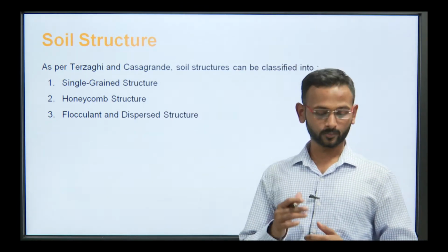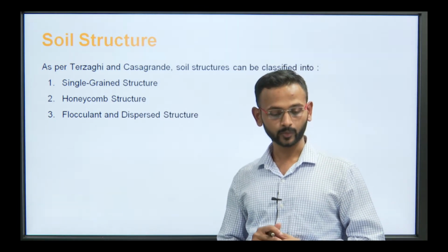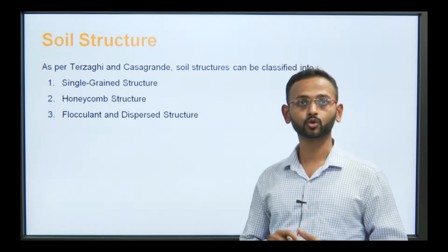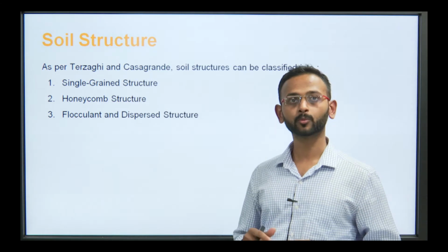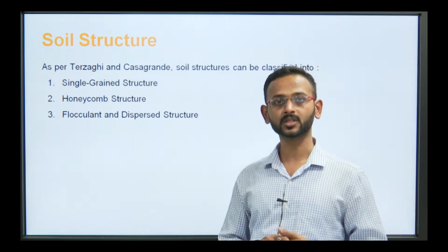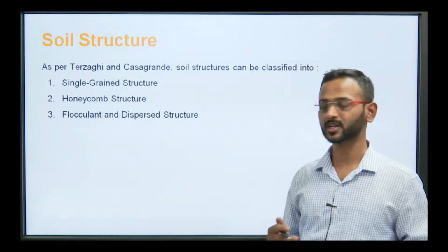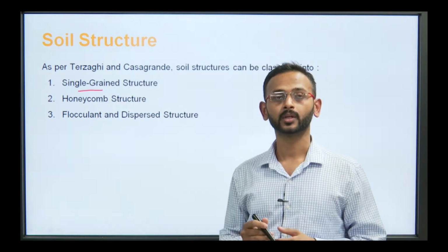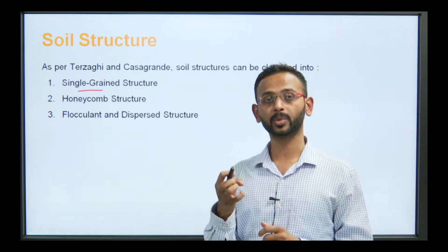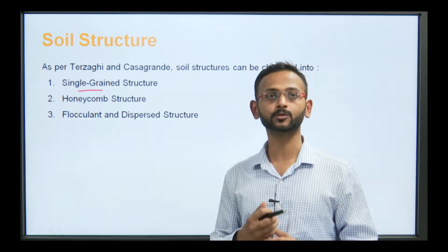Now moving on to this, as per Terzaghi and Casagrande, soil structures can be classified into single grained structure, honeycomb structure, or the third one is what? Flocculent and dispersed structure. As the name suggests, it is single grained, so we will be seeing how these are single grained, and how the arrangement will be.